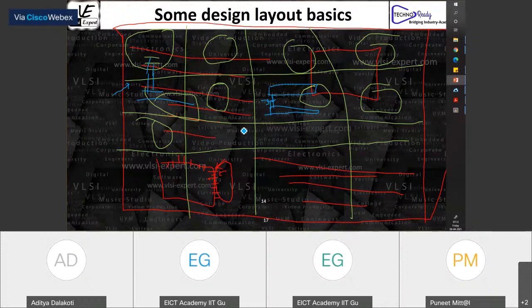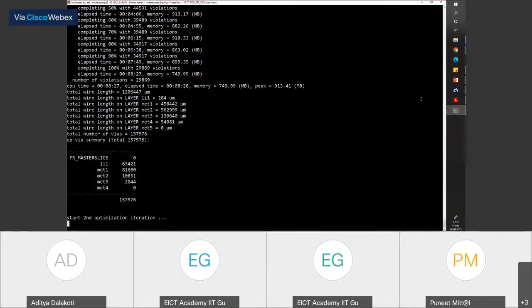So routing is a multi-step process. First, you do a global approximation of the resources, then you bin your design into different parts and again do a routing approximation and resource calculation. Then you do track assignment to figure out which resource will be allocated to which net. Then you draw those nets. And at the end, you fix any issues which come up when you draw them. So stage by stage, you are able to perform different routing tasks. That's why routing takes a lot of time. It's a more complex process than the usual one.